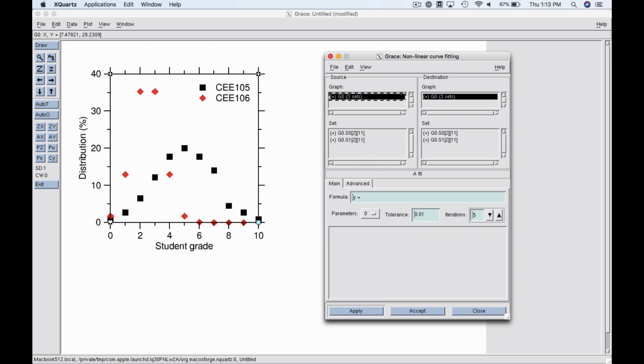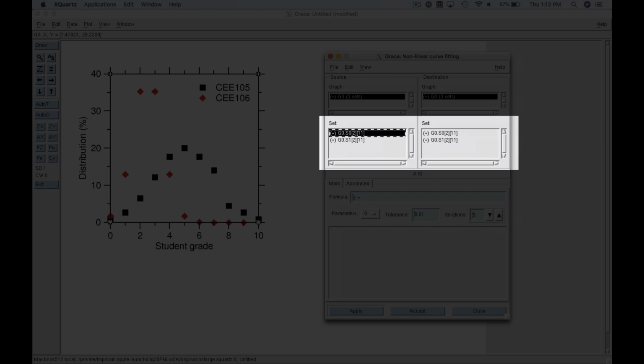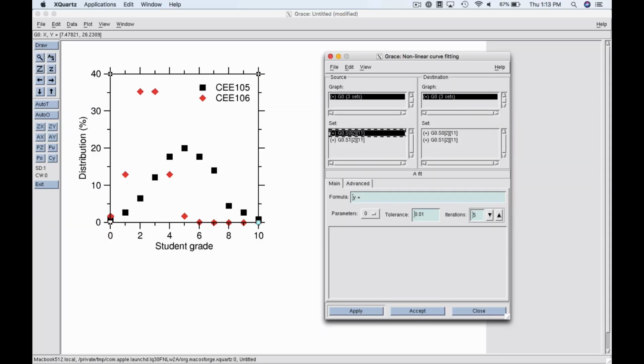So again, you need to select the source of the data that you want to fit. In this case, we want to start with S0. Here again, we are not going to choose any destination, because we want to create a new function that will be the fit of those data. That will be the Gaussian function that is identified by XMGrace as being the best Gaussian function that goes through those points. So here, you need to select the formula that you want to use.